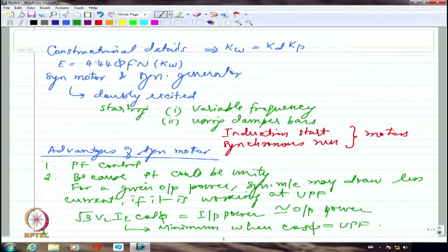It will rotate normally about an axis, but there may be a little torsional motion which may go and hit the stator if there is not enough leverage or enough margin available. So in the case of synchronous machine, I would be able to use those synchronous motors even in those loads where I may expect some amount of torsional motion or some amount of vibrations in the rotor.